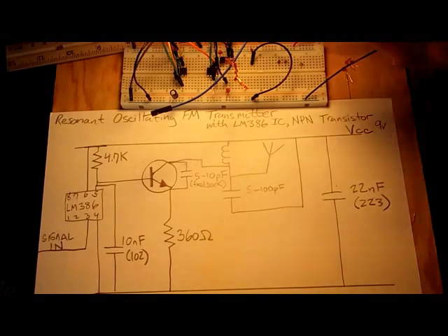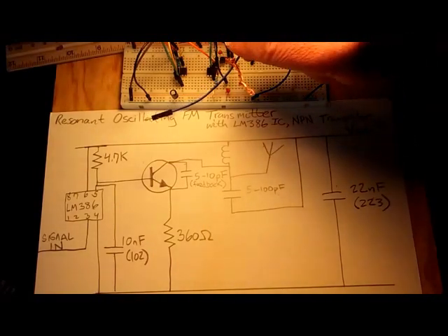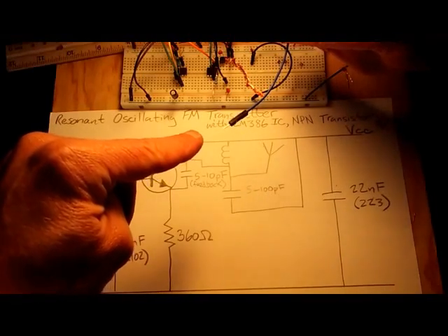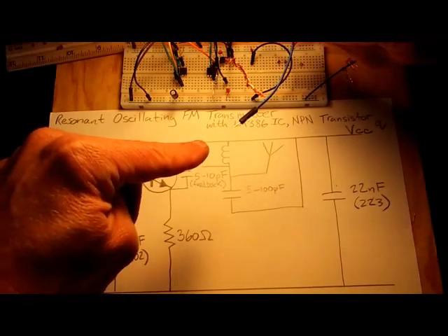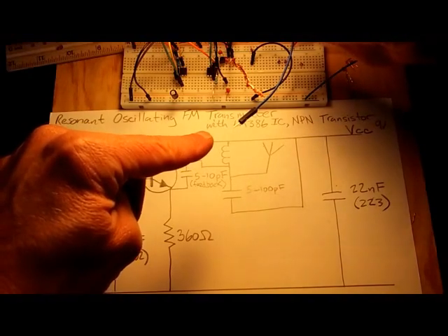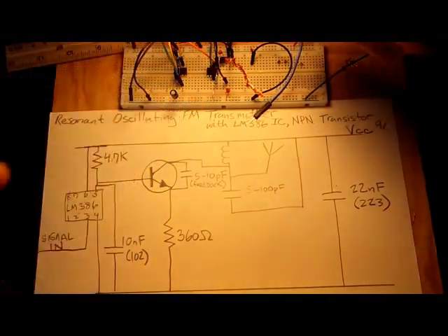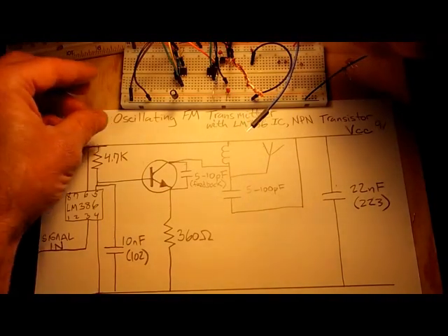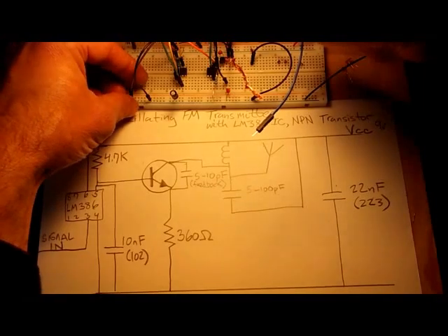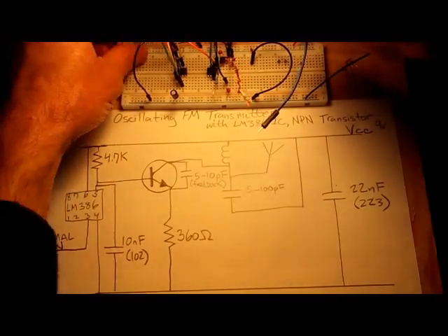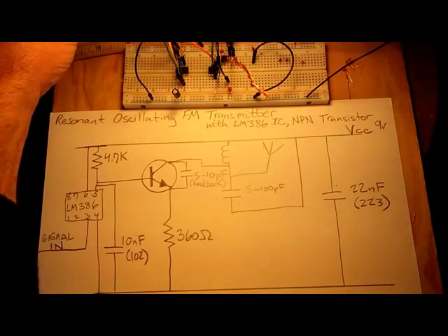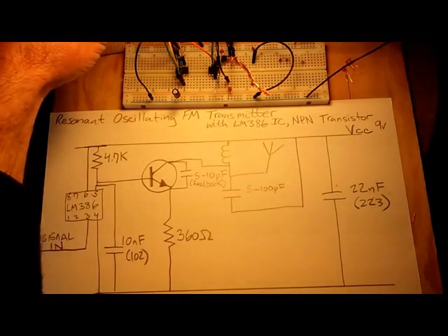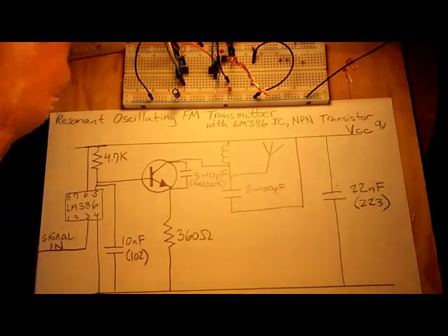right here. And that sound that's coming through the 8-ohm speaker is being picked up through this lead coming off the LM386 amp module. That's acting as our receiver antenna right there. And there's our antenna coming off the transmitter. So just to give you a heads up, that's the signal we're transmitting today, and we no longer need the amp module. It's handy to use the amp module though when you're troubleshooting getting your transmitter going. So it's quiet right now, but that transmitter is transmitting the signal.